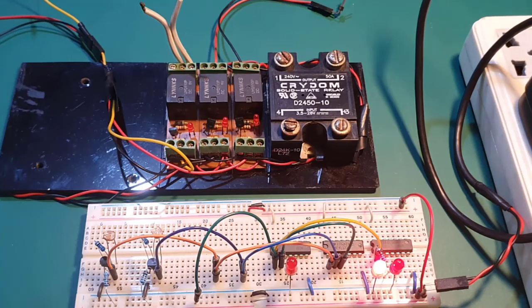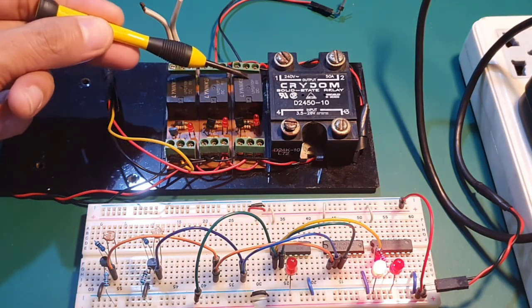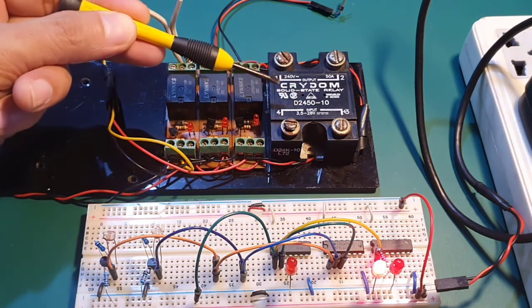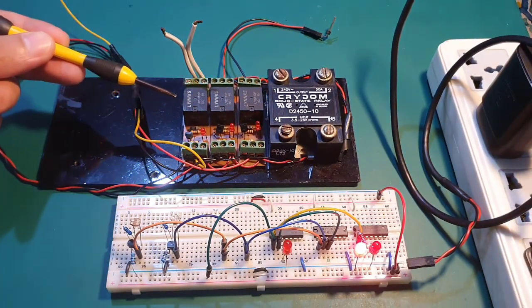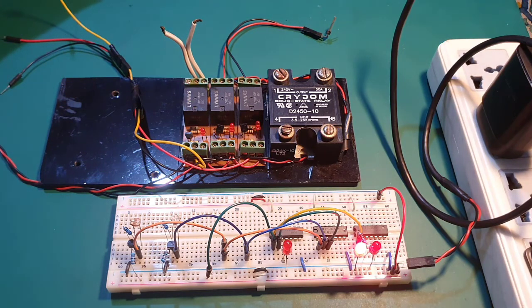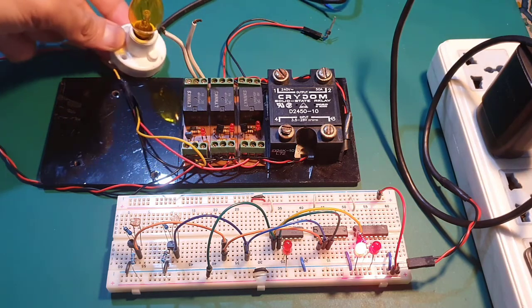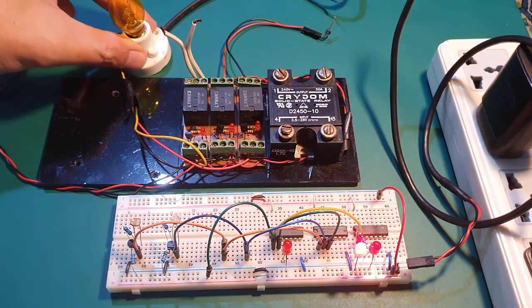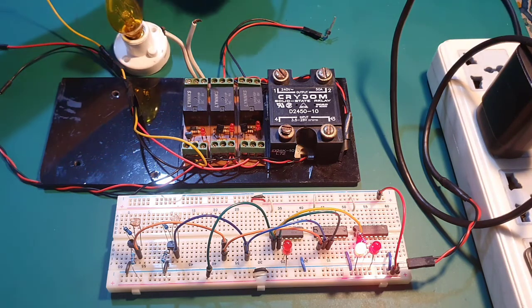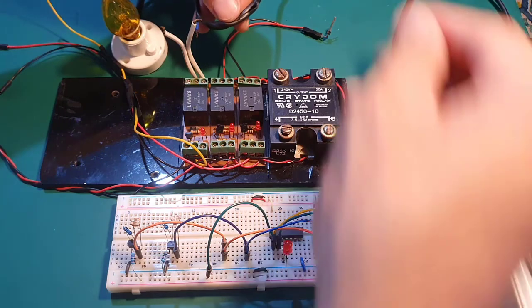For now, all you need to know is that these 3 small block plastics here are what we call electromechanical relays, and this big one here is a solid-state relay. This is purely electronics. You must understand that digital circuits like this combinational logic circuit that we have only operate at lower voltage, 5 volts and below, with a lower current as well. It is primarily used only for logic control and not for driving high voltage and high current devices.